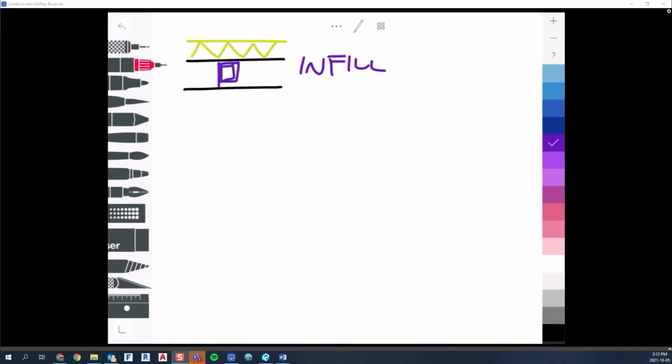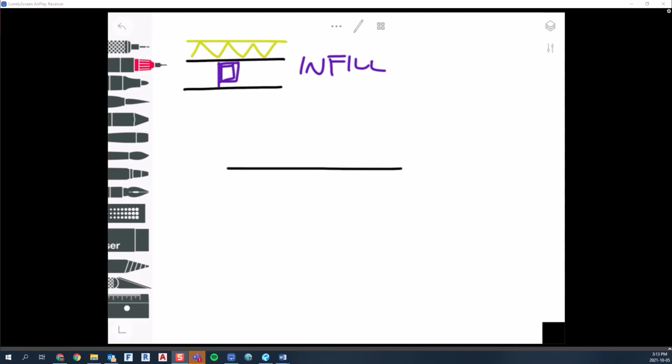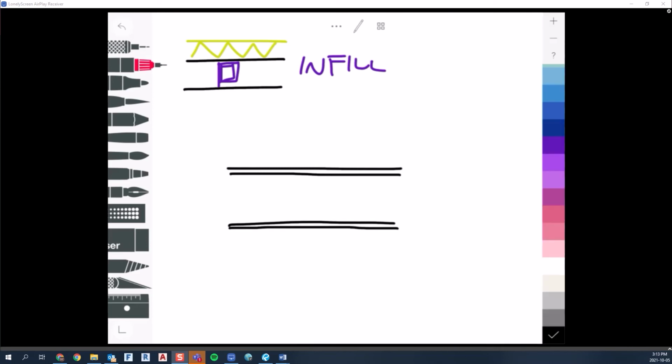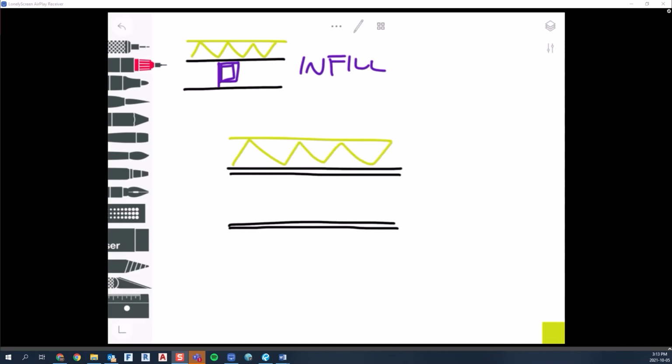Okay, so now let's look at the other situation that's quite common. I've drawn our little infill wall system there just for reference as we look at this one. Another approach is to do this. Here's the sheathing on the outside of the building. Here's the gypsum board on the inside, and this is in plan view again. Our insulation's out here like this, and of course we have our air vapor moisture barrier on there as well. And studs are in the wall, something like this.